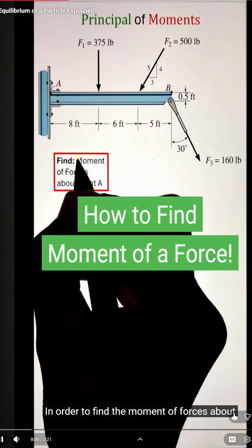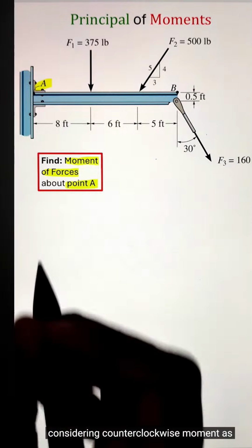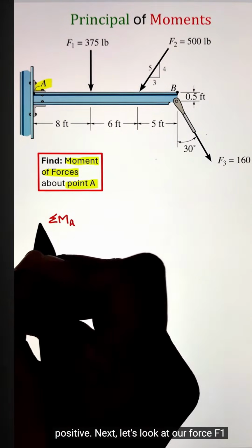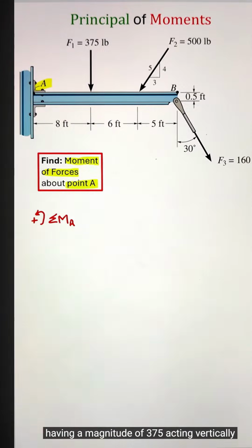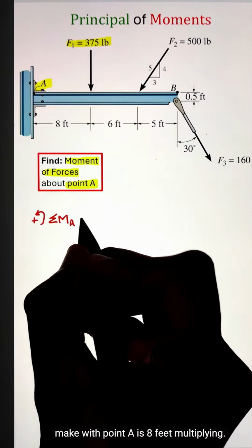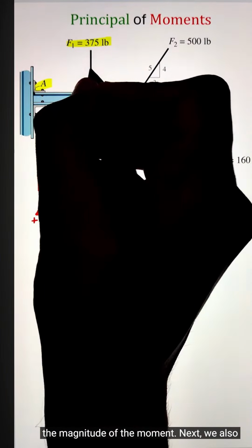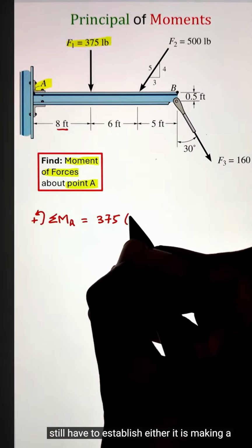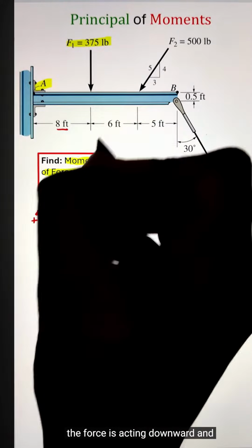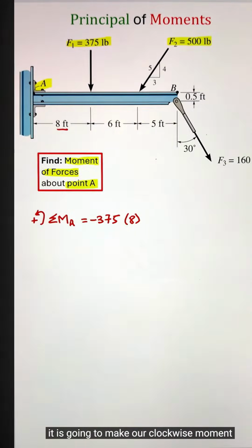In order to find the moment of forces about point A, we can start by establishing our sign convention. In this case, I'm considering counterclockwise moment as positive. Next, let's look at our force F1 having a magnitude of 375 acting vertically downward. Now, the moment arm this force makes with point A is 8 feet. Multiplying the force with its moment arm will give us the magnitude of the moment. Next, we still have to establish whether it is making a clockwise or counterclockwise moment. Since the force is acting downward and the moment arm is to the left of the force, it is going to make our clockwise moment.